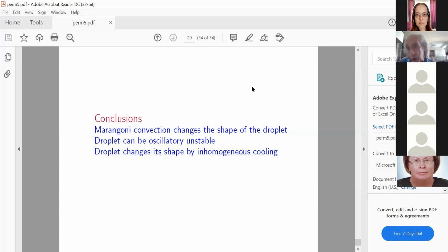threshold, for the usual Marangoni number, the threshold is about the Galileo number. And only for a very thin film, smaller than millimeters, tens, hundreds of micrometers, this instability which is considered here prevails. Otherwise, you have to consider the full three-dimensional instabilities, because it is only for long wave instability.